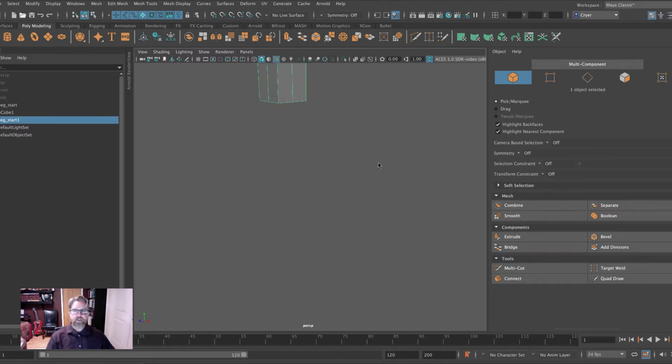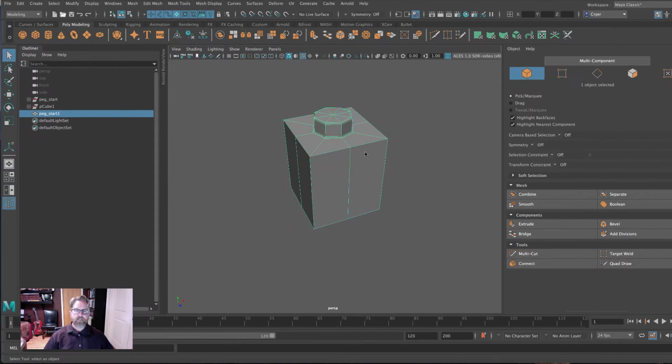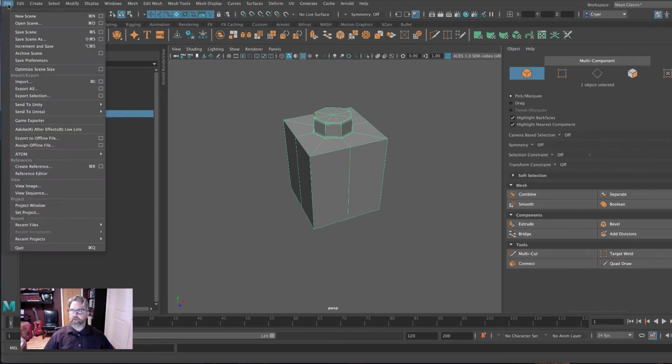The second reason you want to maintain a base unbeveled version is so that we can make a duplicate and combine this and create additional versions. So we could create a 1x2 by combining these two versions. So let's do that. What you would want to do is come and say File, Export, and you can begin to build a library of your bricks and plates.